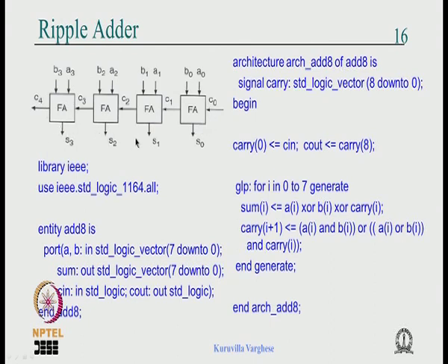But if you go by the principles you have learned, if you want an 8-bit adder, then you make a truth table for A and B which are 8-bit, so it will be a 16-input, 64K truth table. One definitely cannot work that out on paper. Then you implement a circuit which essentially gives you an AND OR circuit which is 2 level or 4 level or whatever, depending on the complexity.